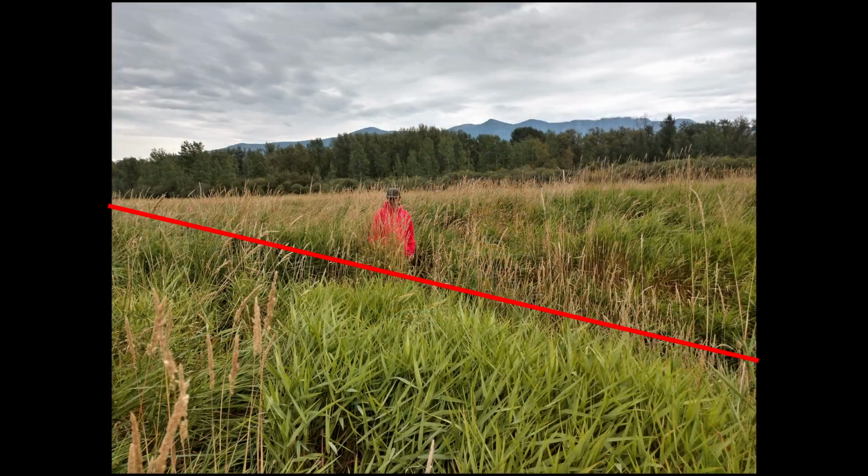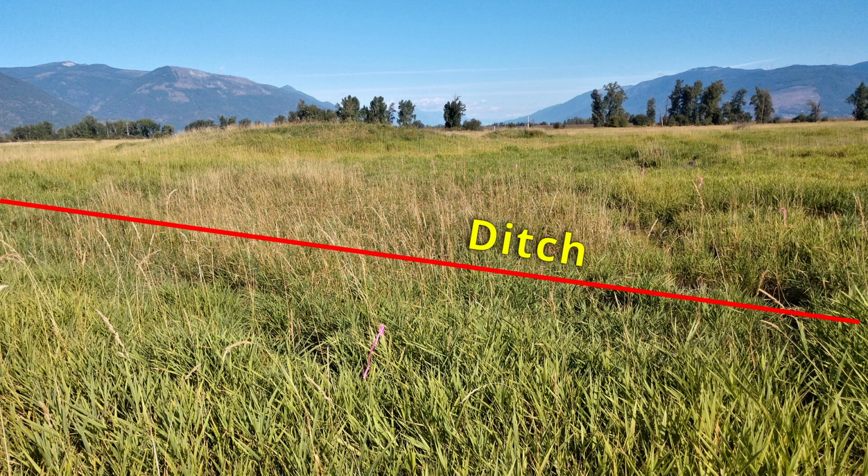The red line shows the location of a ditch that was dug to drain a wetland on the Yakan Nuki Lower Kootenai Band Reserve near Creston, British Columbia in Canada. The ditch appears deepest where Norm Allard is standing because this is where the ditch cuts through the natural rim of the wetland. We're going to construct a groundwater dam to block the water flowing in this ditch to restore the wetland. The pink-colored plastic ribbons were hung to show the heavy equipment operator the center of the ditch to be filled.